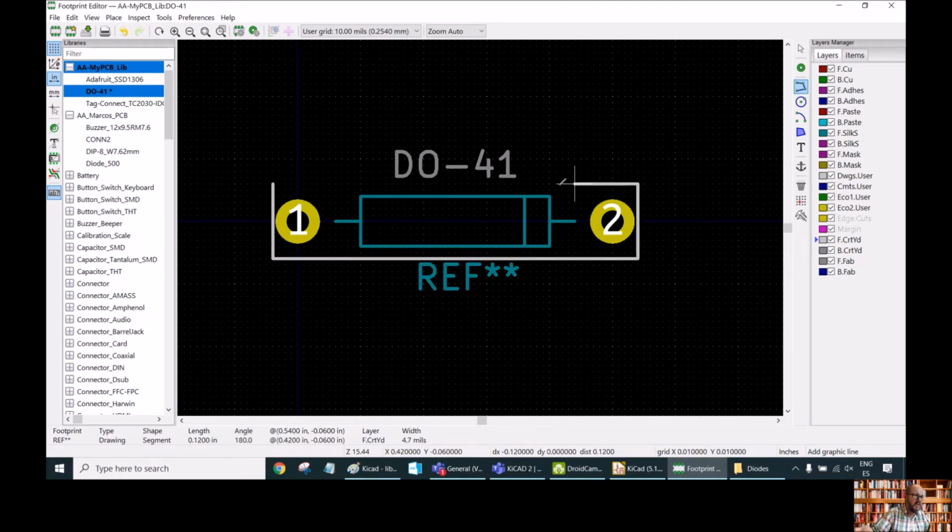Okay, this is very interesting for later checking that there are not components that are too close together, which would make the manufacturing of the board difficult. So this is important because we can use this later to do the checking of the different rules, and it is going to detect if two components are too close. So let's save now, and we are ready to test our two components in a new design.